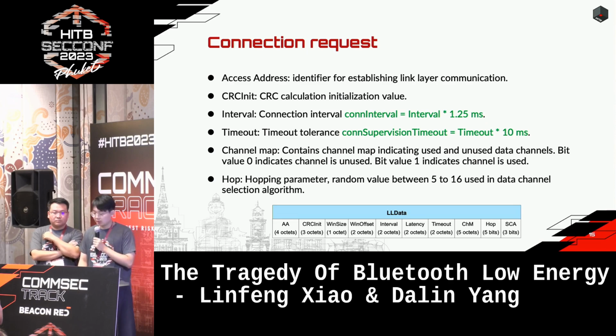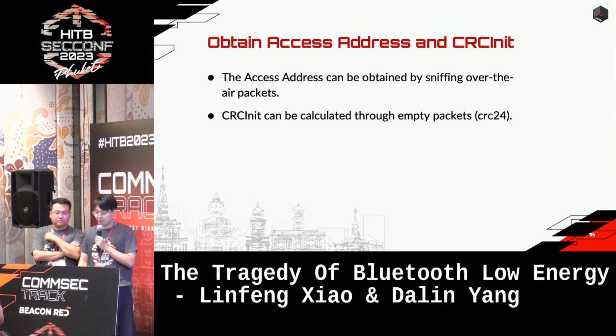So how does BLE communicate? This parameter is, in layman's terms, defines how often BLE hops frequencies. And the timeout is a timeout tolerance. Wireless protocols need to set a timeout mechanism. Once the time is exceeded without a response, the connection is considered disconnected.